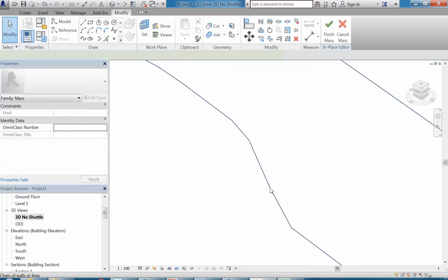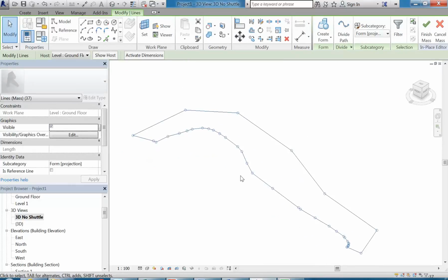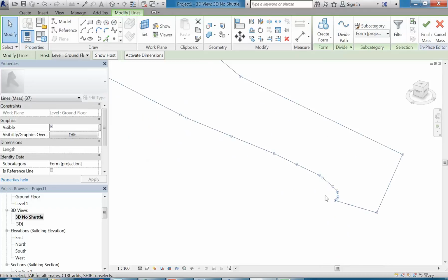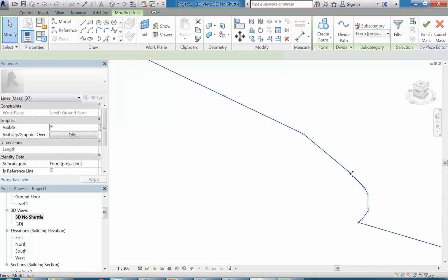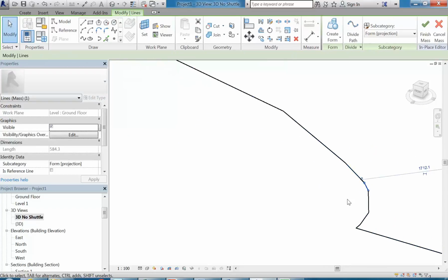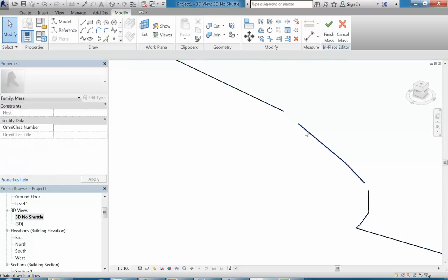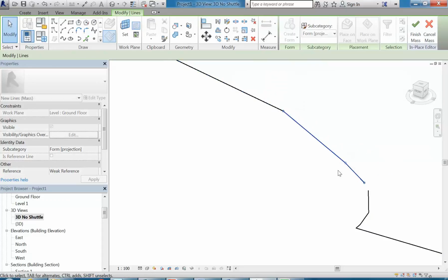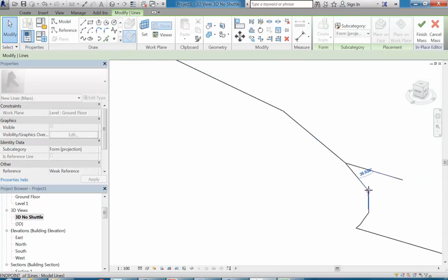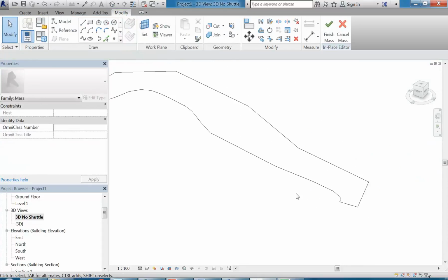And a really good tip I can give you, when you're using solid mass modelling, it'll help you a lot if you get the base shape pretty close to what you want it to be in the end, rather than trying to modify it too much after you've extruded it. You can modify it, but because you have a lot more options, it can be a bit more difficult.